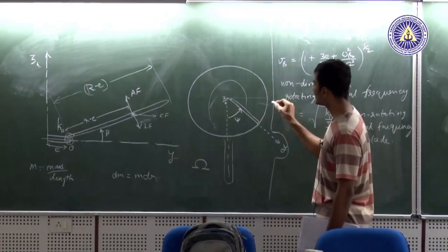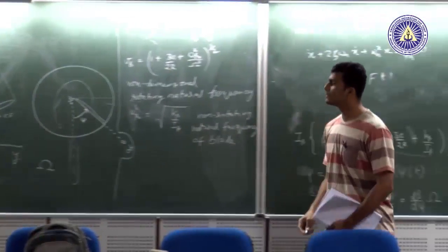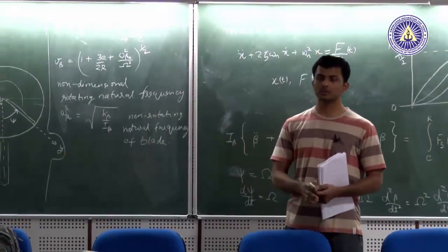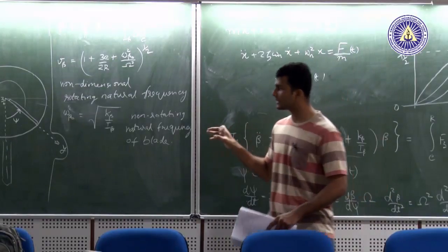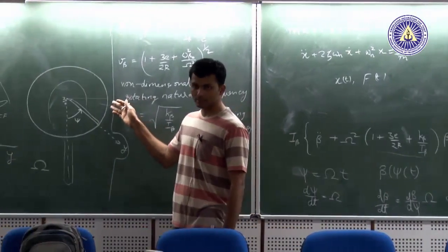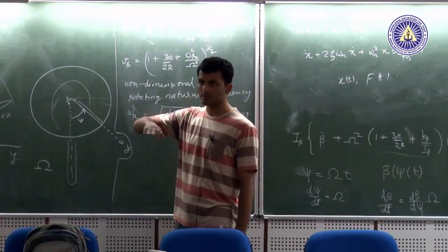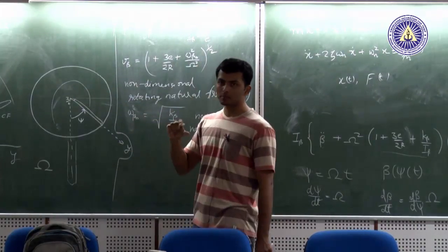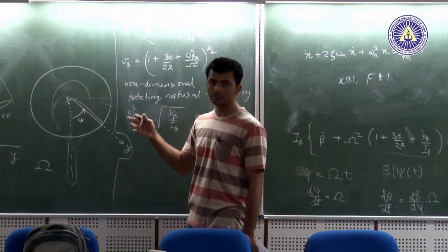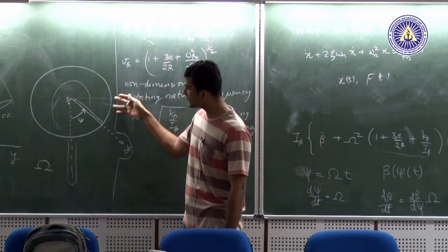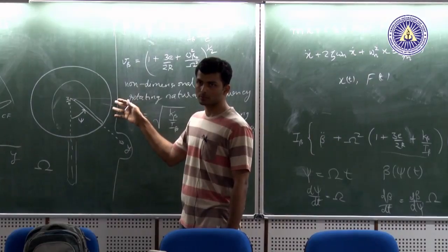Okay, so this is interesting because when you consider tracking problems for helicopters, you need to know where exactly your maximum deflection is happening on the rotor. Otherwise, there will be some amount of tracking error. For attitude stabilization problems, this phase shift will not cause much of a problem.